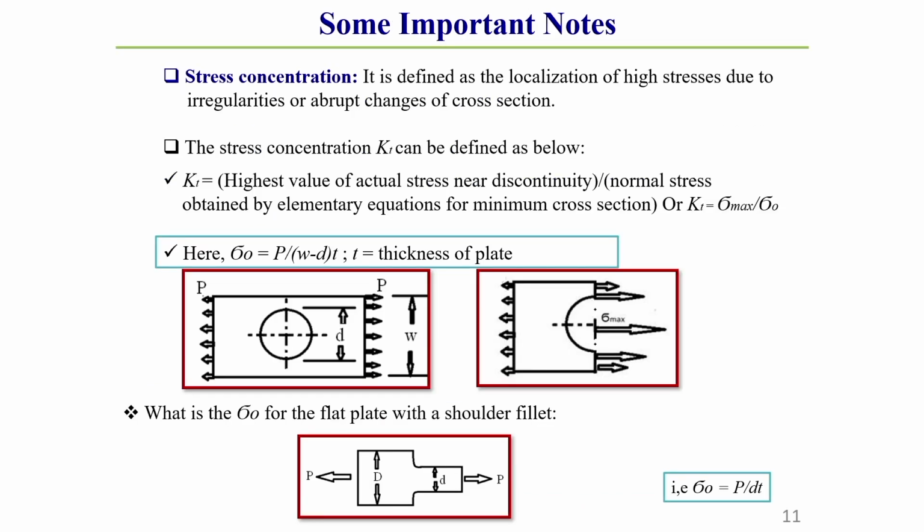Now, we will discuss the Ke value. I have already discussed that the Ke value is called the load factor. This load factor is 1 for the reverse bending case. This Ke value is 0.85 generally for axial types of fluctuating or reverse load, you can say axial loading case, and 0.59 generally for the torsion case. I have already shown this in the first slide itself.